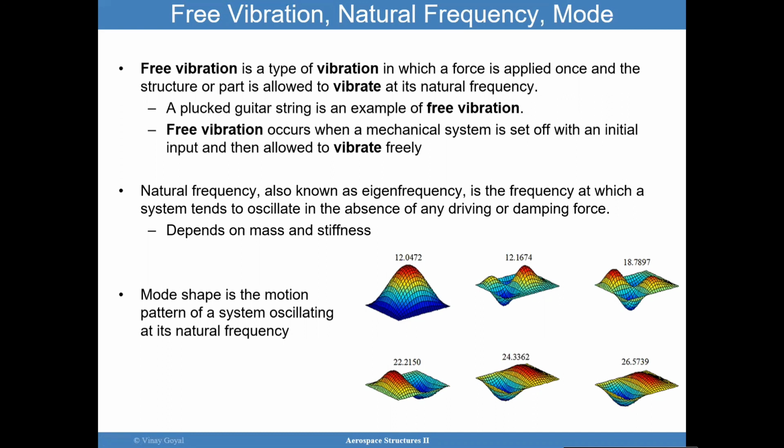And I want to point out something very, very interesting. The interesting part here is that every structure has a unique DNA. I want you to think about it in that manner, because each structure is going to have a particular dynamic characteristic. And that dynamic characteristic is going to be composed of these frequencies and then these mode shapes. So think about that as we go through.